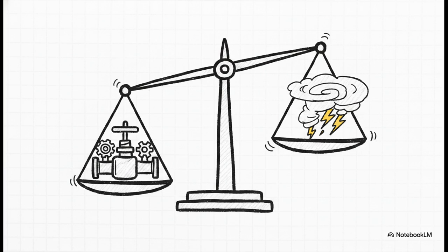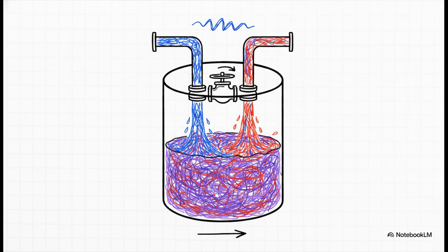Instead of trying to control individual flow rates completely independently, the controller's main objective is to just lock in the specific mathematical relationship between the two. To ground this math in reality, think about continuous blending operations. If you're mixing two liquids together to create a specific chemical product, you don't necessarily care if the total volume fluctuates a bit, but you absolutely care that the ratio of chemical A to chemical B remains exactly perfect. If the unmeasured disturbance flow increases, the manipulated flow must automatically increase to match that exact ratio. It's all about keeping things perfectly proportional.